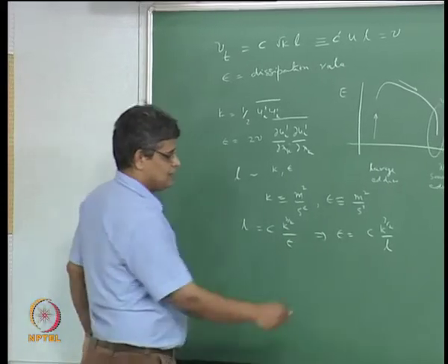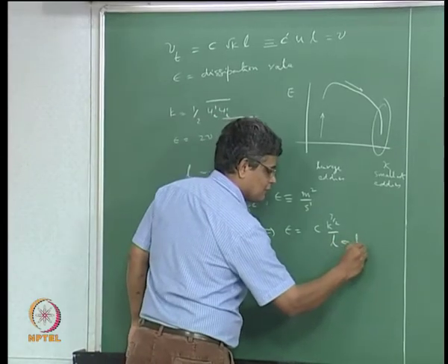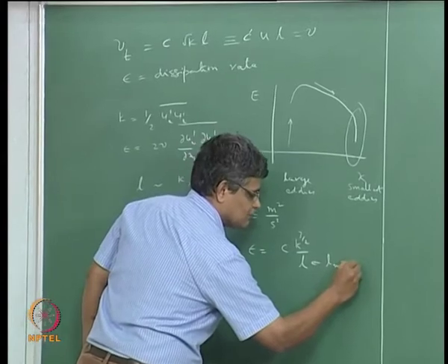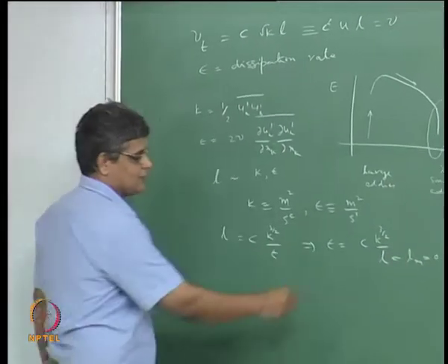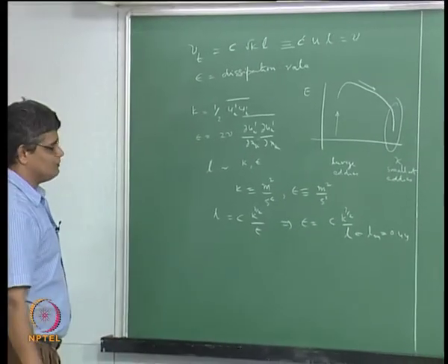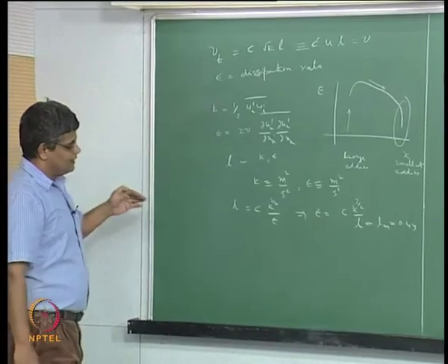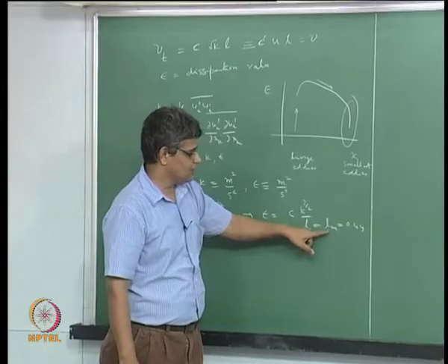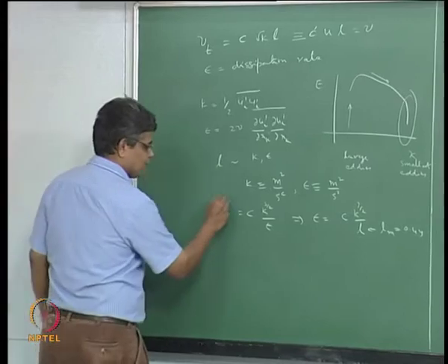So we say that we replace this with the mixing length model, and therefore we say that this is, for example, equal to 0.4 times y, where y is normal distance, and this constant is adjusted for best fit with the data, and then we have an overall model. And we know that in this way we have a problem with the specification of the mixing length, and we make use of this very factor here